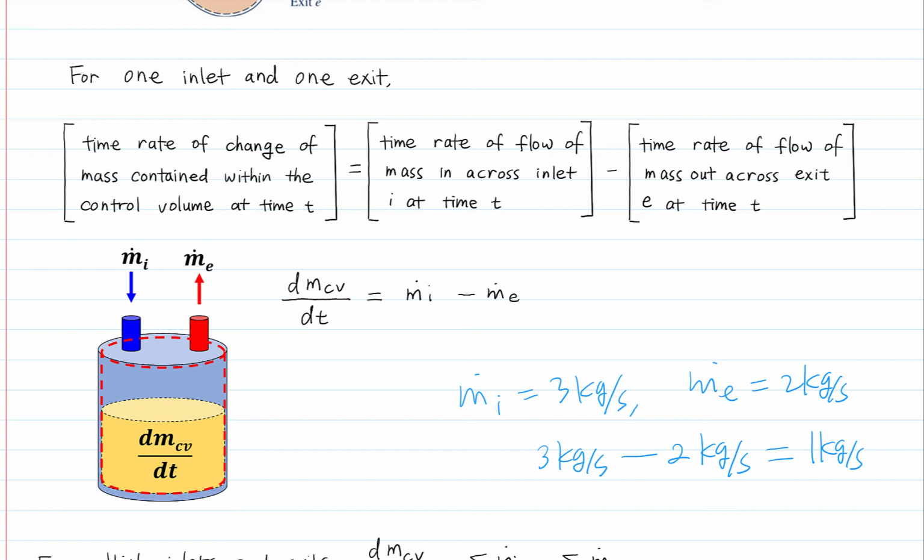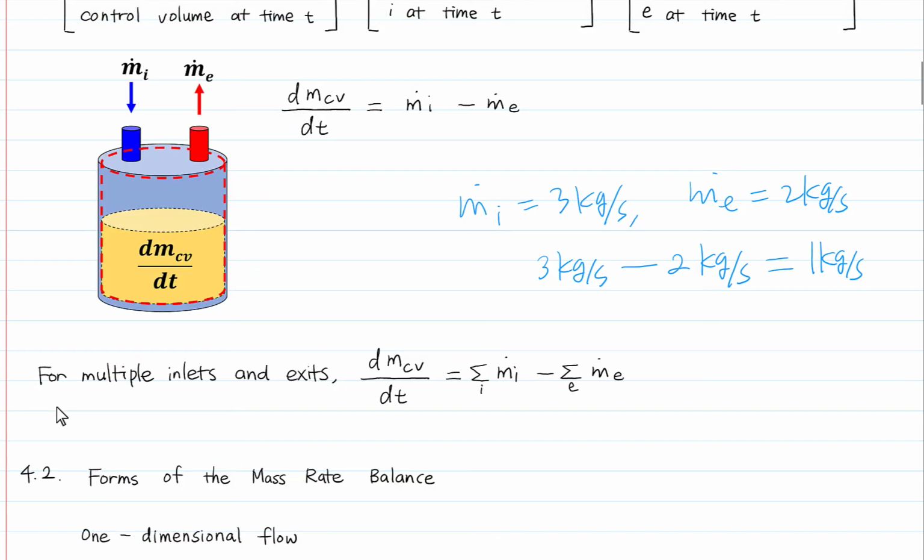If the mass flow rate m dot in is equal to m dot out, the mass of the system remains constant. The control volume may have several inlets and outlets, and the summation is used to evaluate the total mass transfer across the system.